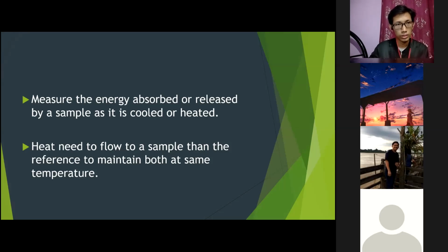DSC also measures the energy absorbed or released by a sample as it is heated or cooled. According to Instrument Specialists Incorporated, the basic principle underlying this analysis technique is that when the sample undergoes transformation, such as a phase transition, more or less heat will need to flow to the sample than the reference to maintain both at the same temperature.